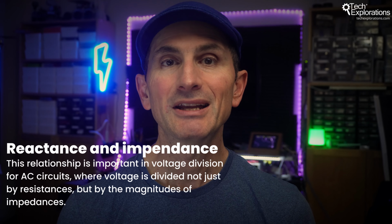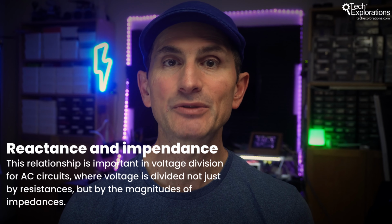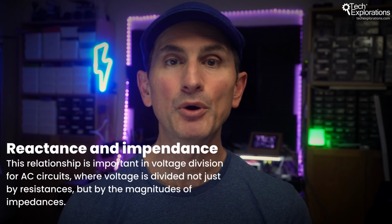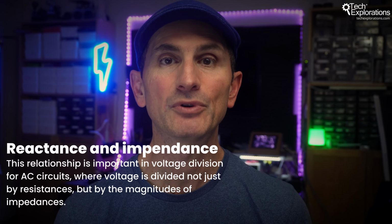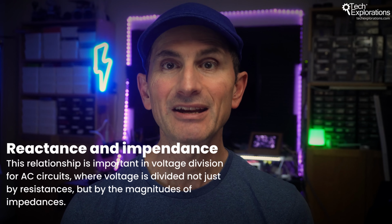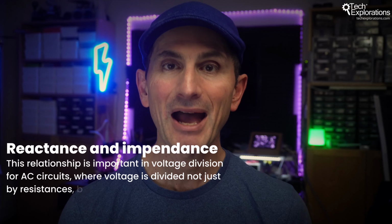For example, in an RC voltage divider, the output voltage depends on the relative magnitudes of R and X_C, both of which determine how the input voltage is split. Now, understanding the role of reactance as a component of impedance helps explain how capacitors and inductors influence circuit behavior at different frequencies, and why voltage division formulas in AC analysis use Z instead of just R.